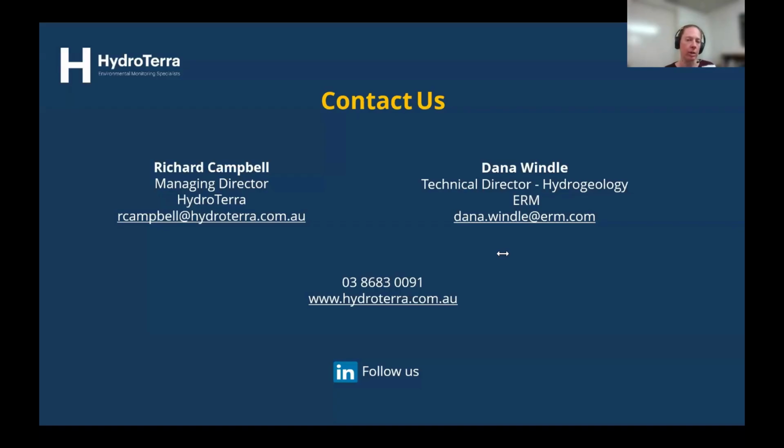I'm sure there's much more sophisticated equipment that Richard could talk to as well. Yep. So there are several methods. I'd probably steer towards our website, to be honest, because there's quite a few different technologies for it. Some are contactless, which are really useful, so you can keep things out of the water, and on a lot of sites where you get big storm events, contactless sensors are really valuable. You can even get contactless sensors to measure flow these days. So that's something else to be aware of.